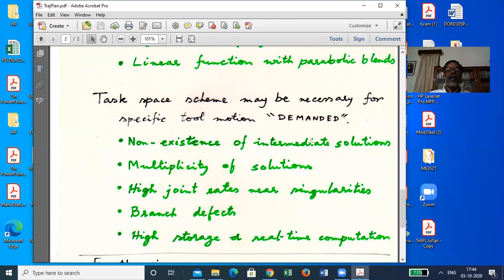Now here you cannot say that, because here it's a completely coupled problem, and there may not be any joint position that gives you a specific intermediate solution for the end effector. So this requires heavy work in the background, offline, beforehand.